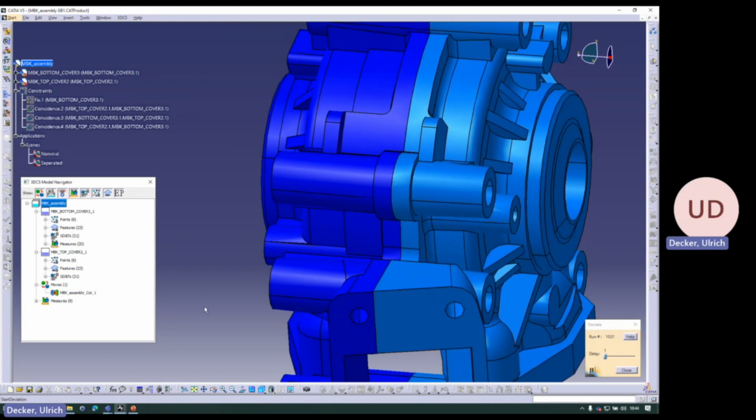This is like in the real world. First, you produce the single parts, then you pick the single parts out of the single part boxes randomly to an assembly. If you measure that assembly, you find a certain value. If you do the next assembly, you never will measure the same, because of single part tolerances, because of geometry effects, because of assembly line effects.